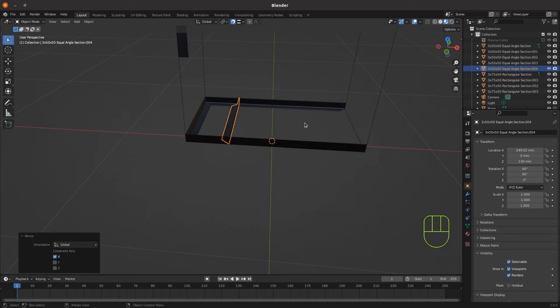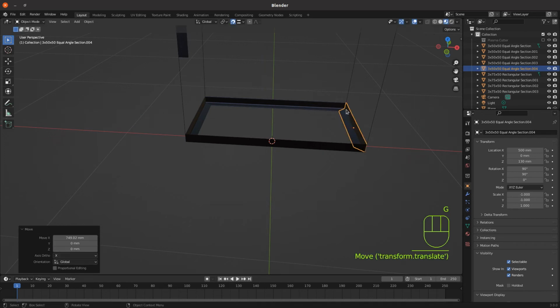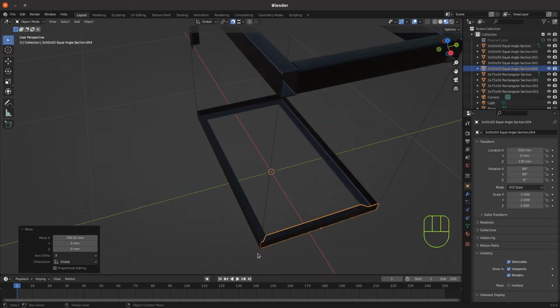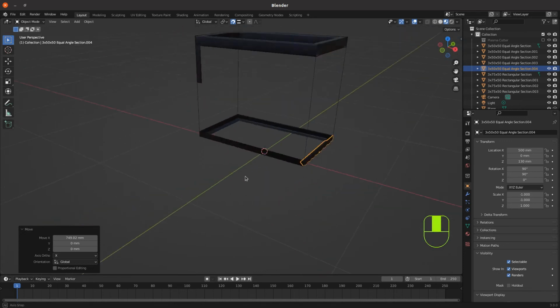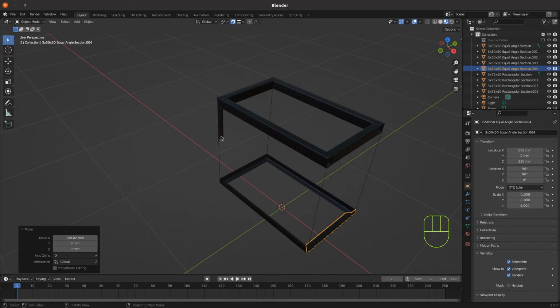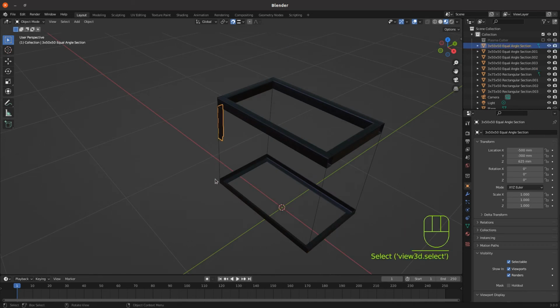So again, grab on the x-axis and snap it onto that bottom edge, and that gives us a very easy way to make the bottom frame and the components to size without having to consider the dimensions, because we took care of that in the outer reference cube. So the last thing to do now is to just modify this one vertical we first put in place.